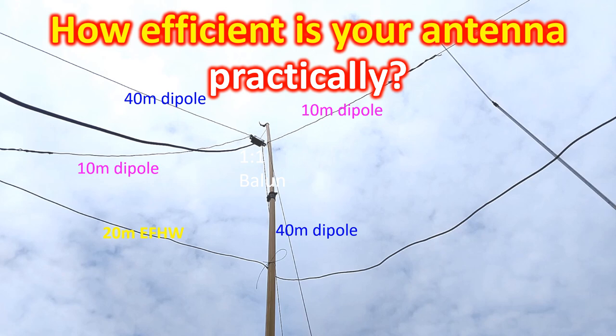Efficiency of the antenna is the ratio of power radiated by the antenna to the power supplied to the antenna. Antennas can be very simple dipole antennas or very complex designs like stacked Yagi-Uda antennas or Cross Yagis for LEO satellite operations. Either way, their basic function is to convert electrical signals to electromagnetic waves and vice versa, depending on whether it is used for transmission, reception or both.